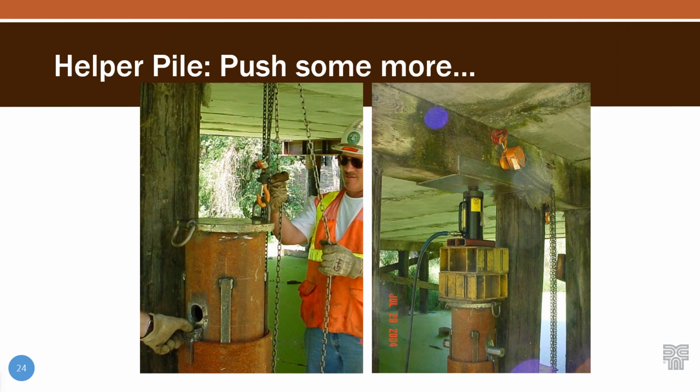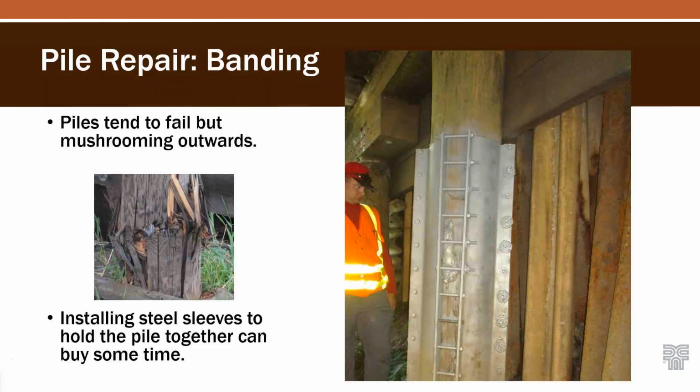You can see that sleeve on the left kind of in action here as they keep going through the jacking process. So it takes a little bit of time, but again, you can do it in water with minimal environmental disturbance. You don't have to shore the bridge while you're doing it. So there's some real advantages to this kind of a helper pile installation.